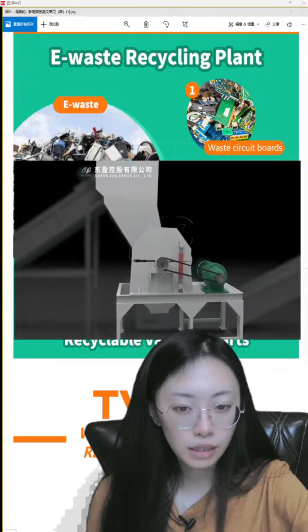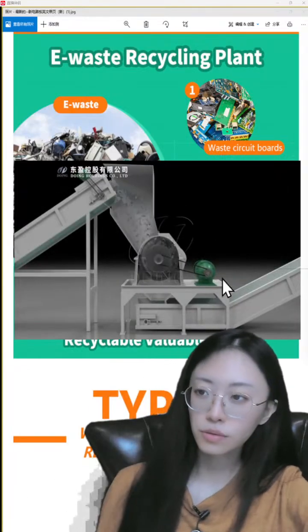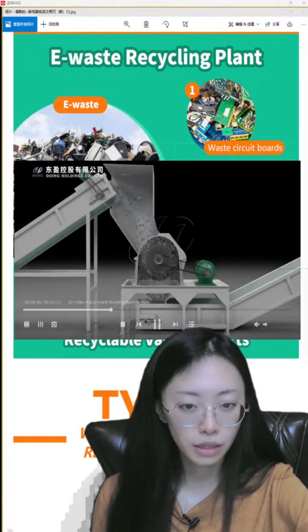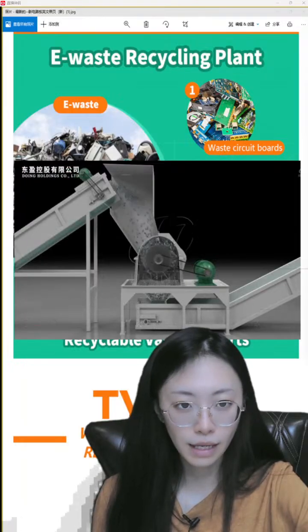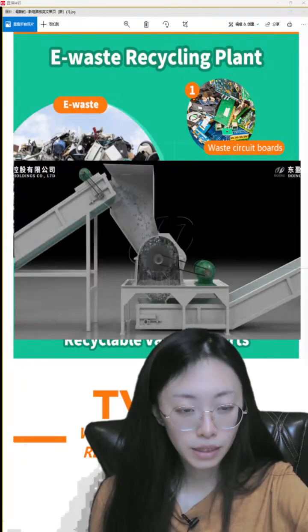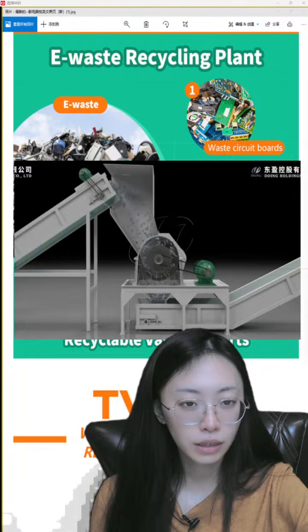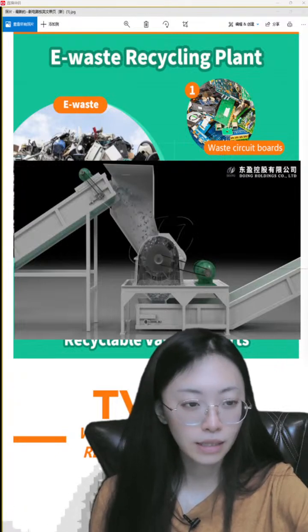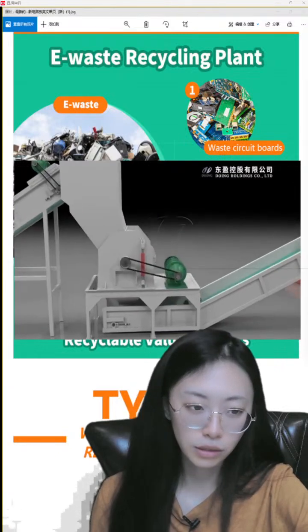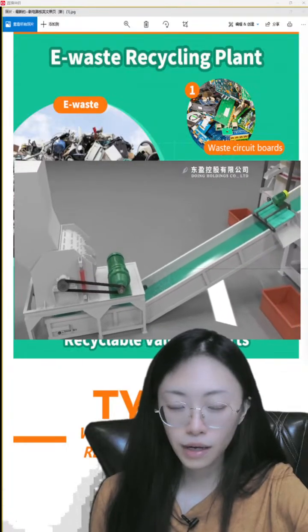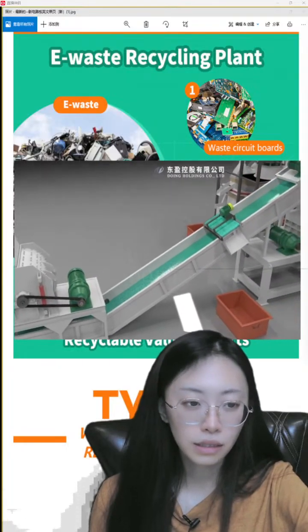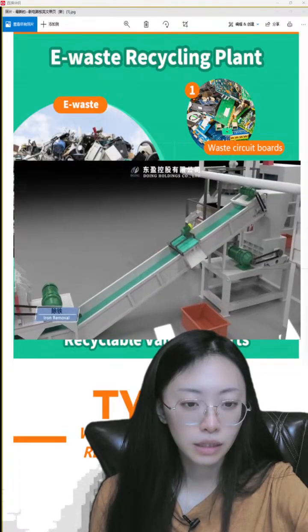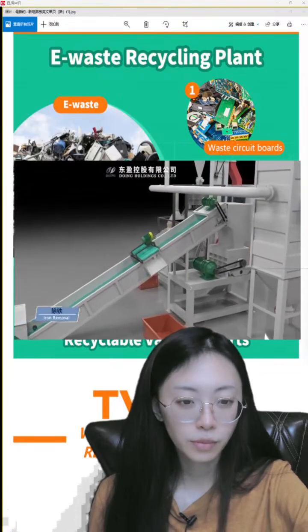In this production line, you can see this is a 3D video of the production. We can process the scrap PCB board, and by using physical crushing and separation, get the metals and resin fiber. I can get the copper and the aluminium from the production.